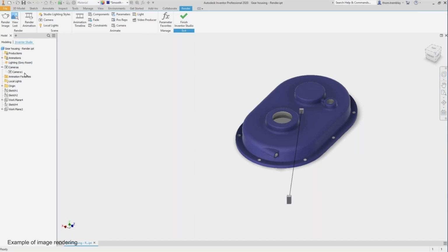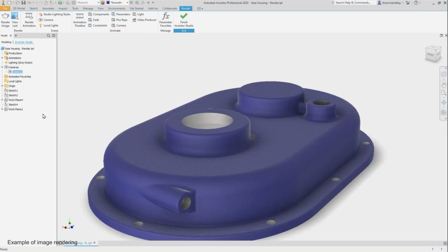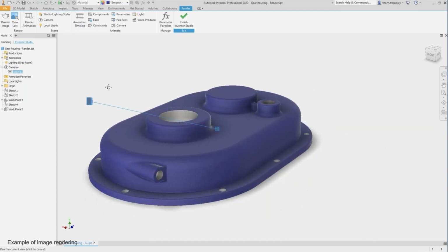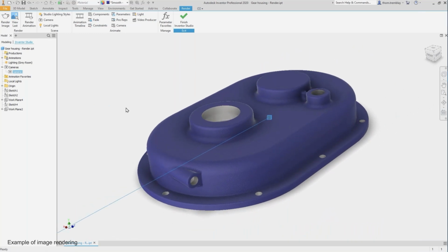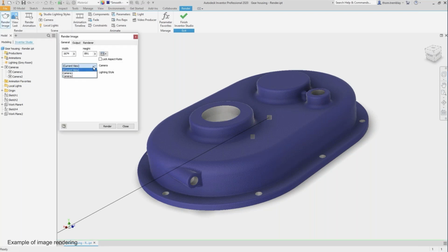We also have some really great capabilities for making and modifying cameras. So here we see the camera view that we had. So we're able to go back and quickly make modifications. We also have the option of just simply setting a new point of view. And then when we find a point of view that we like, we can make sure that we're in perspective view. And then we can just simply generate a camera or create a camera from that view. So rather than going through the more manual process of setting up a camera and a target, we can just simply set a view and build from it. Then in the rendering environment, we can establish what camera we want to base a rendering on.